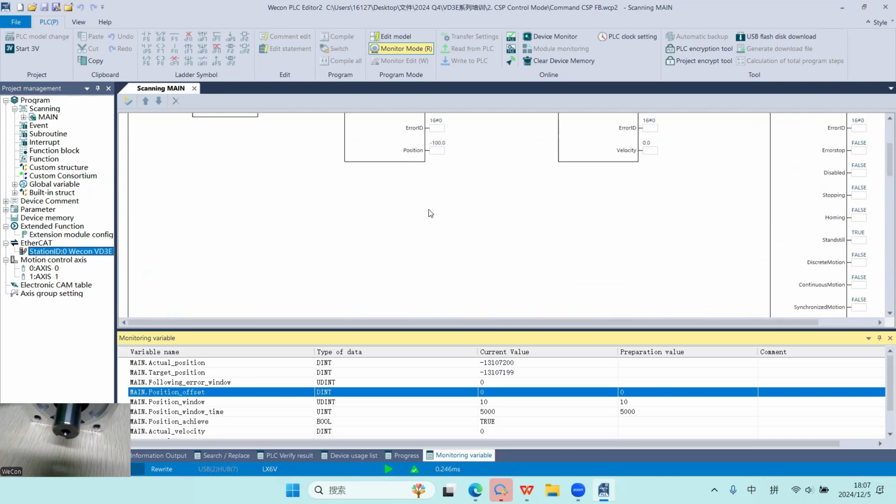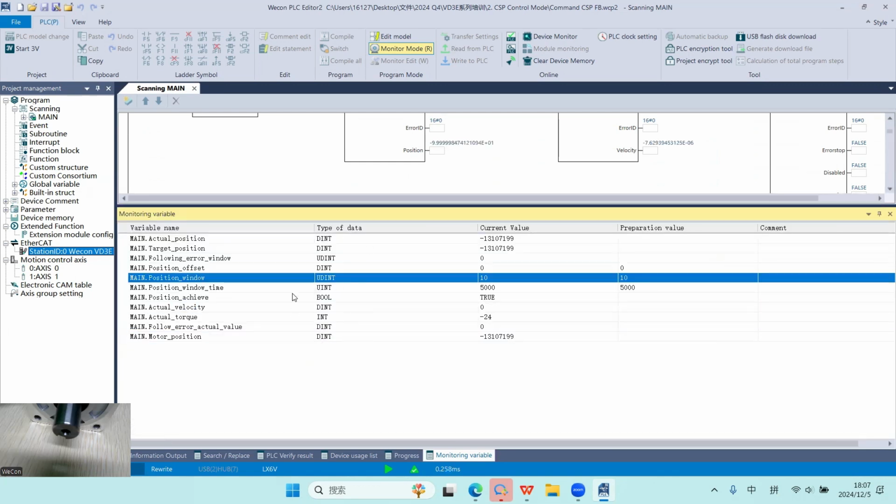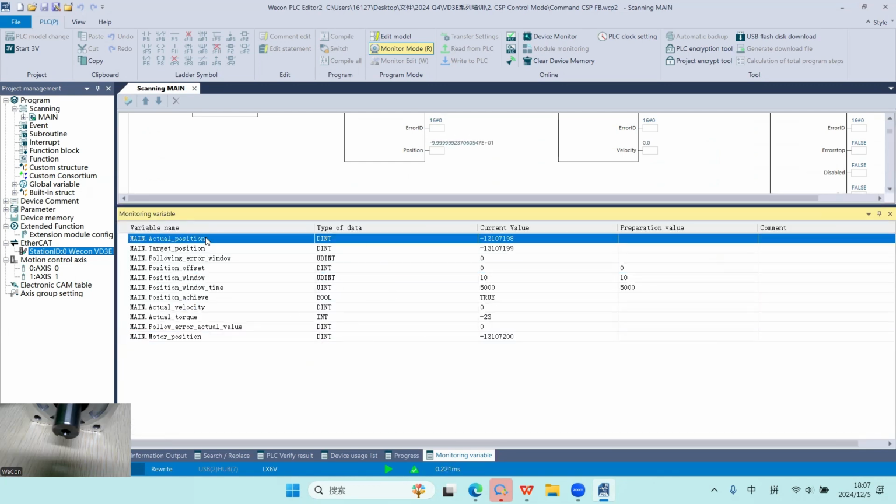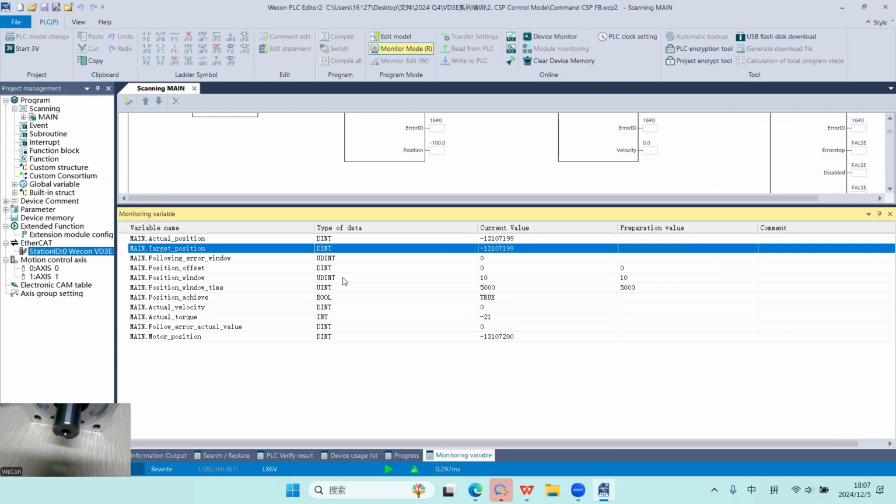But some controllers, for example, not a PLC, just an EtherCAT master, we have to configure these parameters and use PDO to change the value of PDO to enable our driver and change the target position or change the operation mode of our driver.